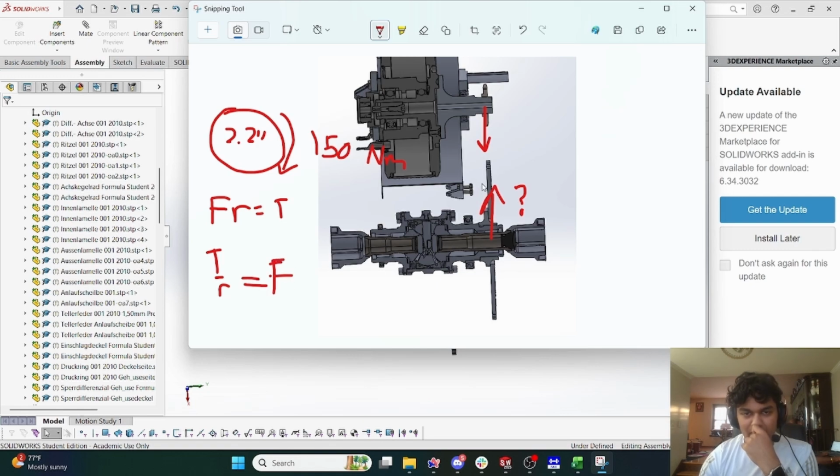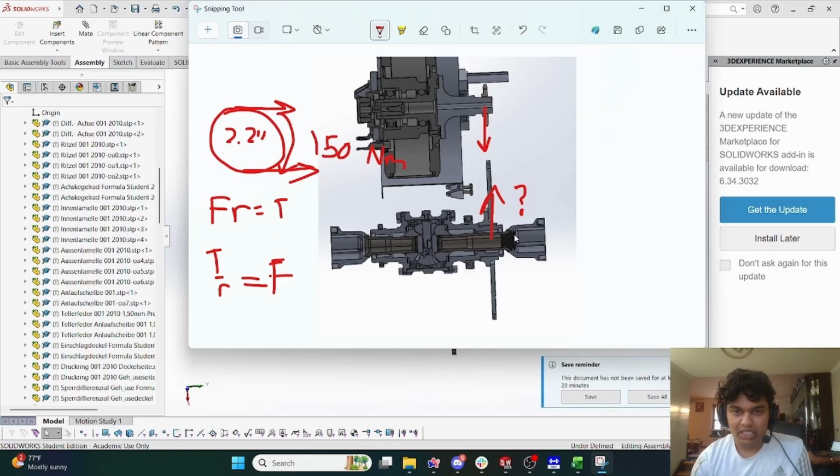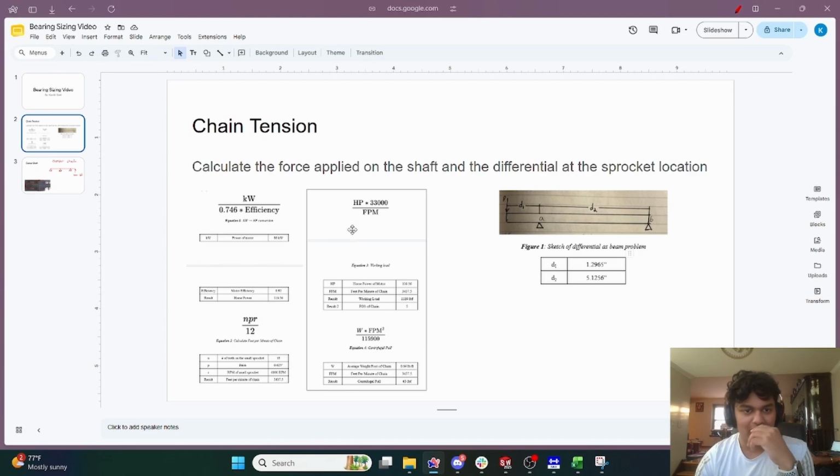This has some approximations with it because we would be assuming that the entire force would basically be applied only in one direction, like this, which is not the case. Load is also applied over here on the slack side, but it's a good enough approximation. The other way we can do it is we can look at the power being transmitted and the velocity that it's going at, and then from there we could calculate the force, and that's the way we've done it.